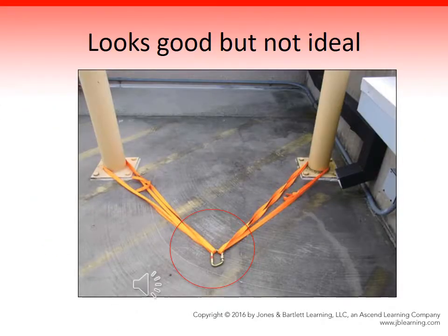In this slide, we see an anchor system that we see quite frequently. Looks pretty good, but if we look closer, we can see that we're loading the carabiner inefficiently and placing a good portion of the force on the gate side. When a load is placed on this anchor, we will load it in all 3 axes, also known as triaxial or 3-way loading. As we will learn, this will cause the carabiner to function in a manner that was not intended, and because of that, it could fail. Failure is always bad in the rope rescue environment.